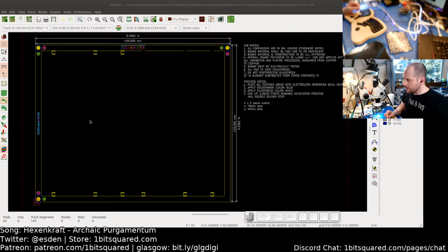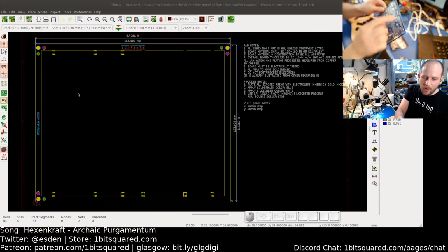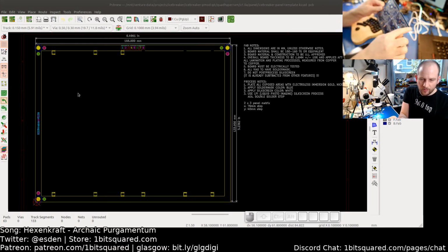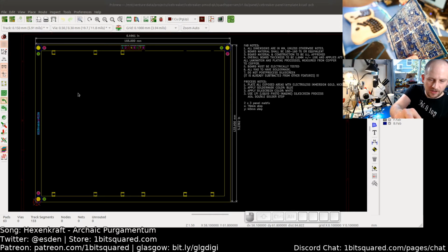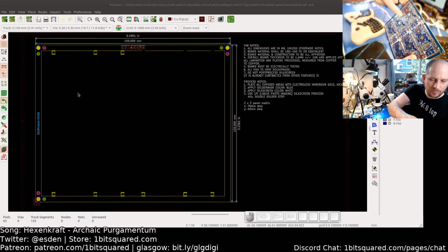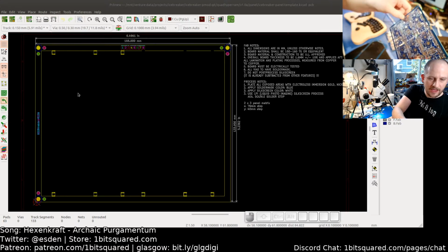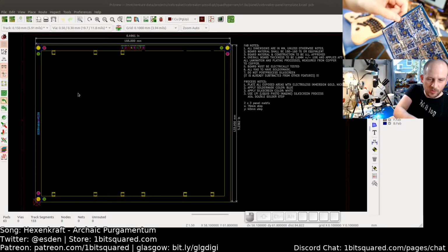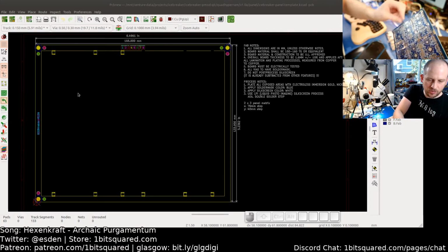And then you will get this. So this is the template that I copied from the icebreaker. How I like having my panels is with a full frame all around the board for rigidity. And then what I also do is only connect with tabs on top and bottom of the boards, at least in this version, because I have these USB connectors that will be hanging out on the side of the board. And so getting in here with the tool to break off the tabs will become problematic.